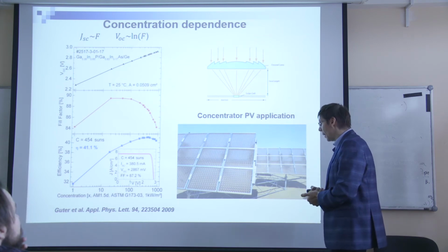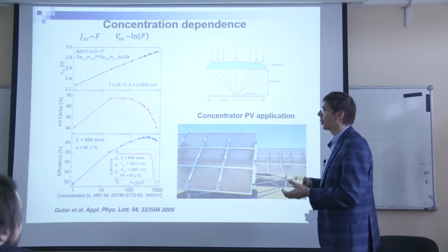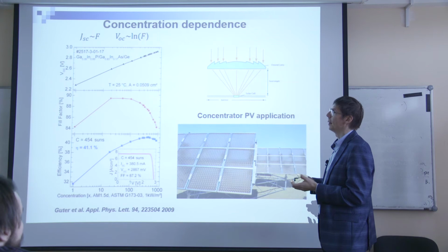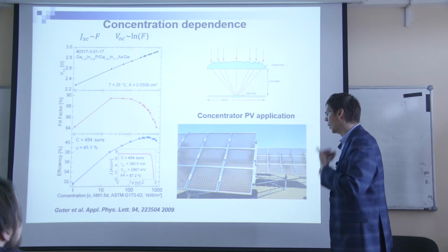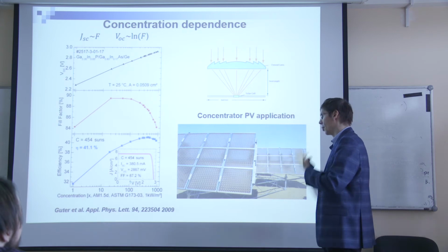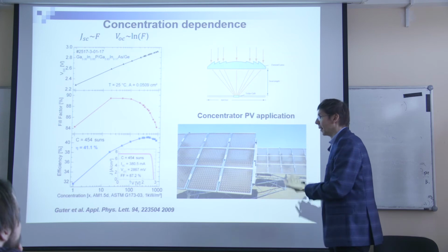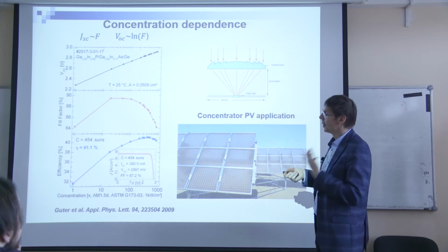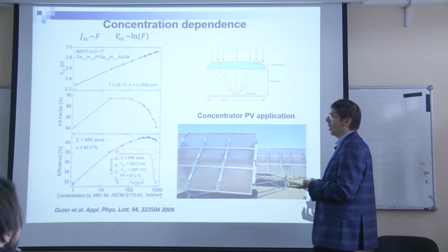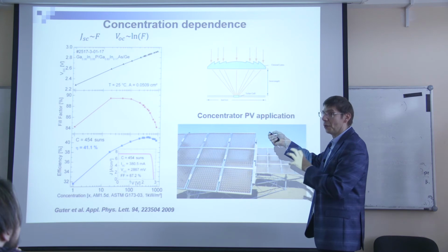And in this case, actually, the value of the short circuit current is calculated from a spectral response, and you know the short circuit current already, and people make an opposite thing. If you know the short circuit current, then you can say which intensity the short circuit current of the measured solar cell corresponds to.